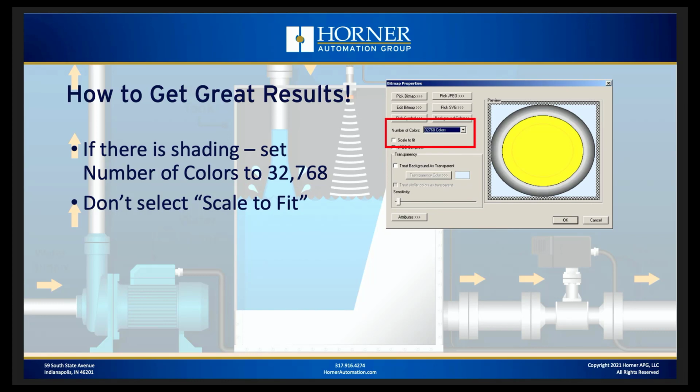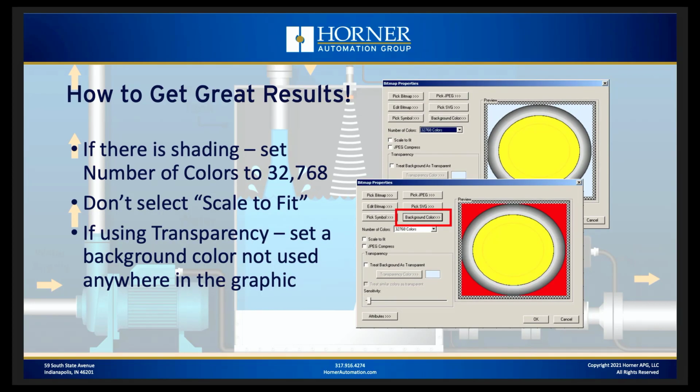So that is the first hint. Don't select scale to fit. And in general, if it's got shading, set the number of colors up to the maximum of 32,000. Next, if you're using transparency, it's especially important to go with a high number of colors so that Cscape can differentiate between the background color and the fill color.